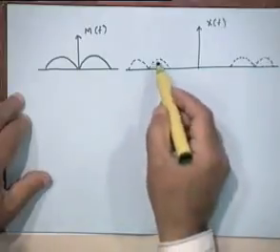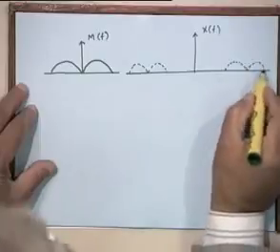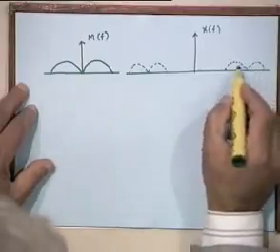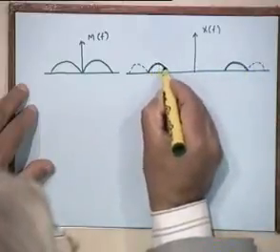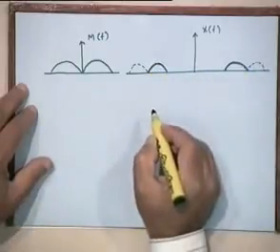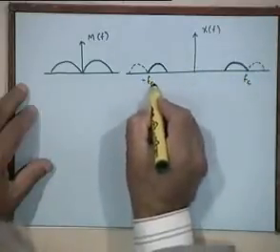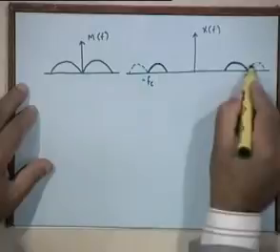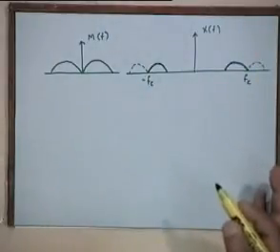What we are saying is we can remove one of the two sidebands. For example, we could remove the upper sideband, right, and transmit only the lower sideband. So, we are transmitting this. This will of course come along with that, right. So, this is around f_c and this will be around minus f_c. So, this portion of the spectrum is being filtered out at the transmitter.